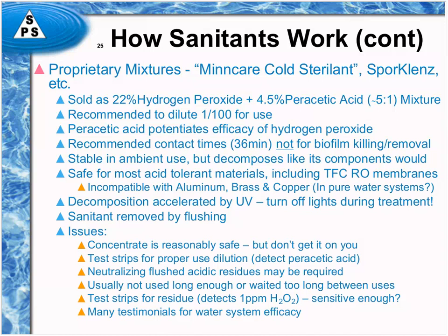There are test strips that usually come with these proprietary products that allow you to test for the use concentration and test for the residues after rinsing. But be careful with the residue testing. It only goes down to 1 ppm hydrogen peroxide, and that may not be sensitive enough for your needs.